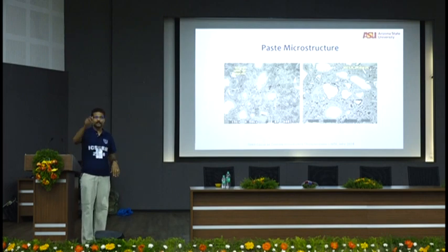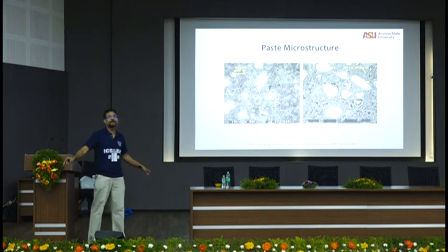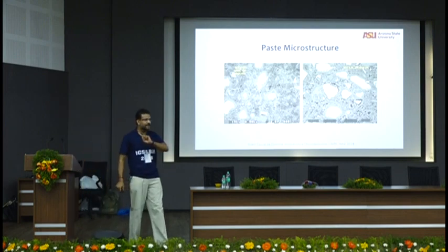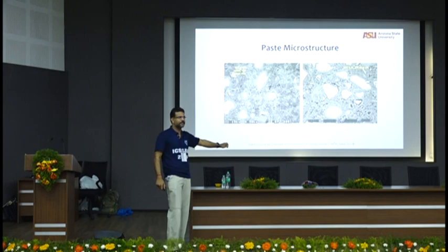Some people plot degree of hydration versus strength. Please don't do it. Okay? That is, degree of hydration and strength have absolutely no relationship unless every other parameter that you have done is constant. So generally when you compare specimens, never do that.